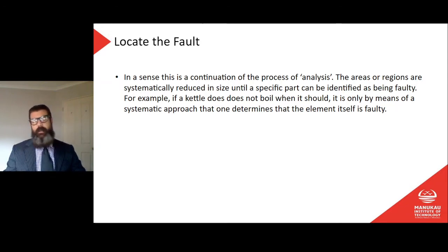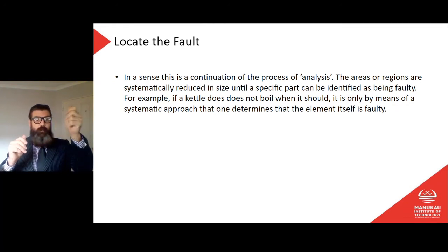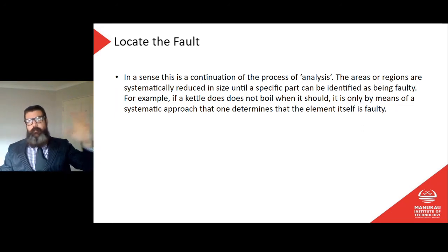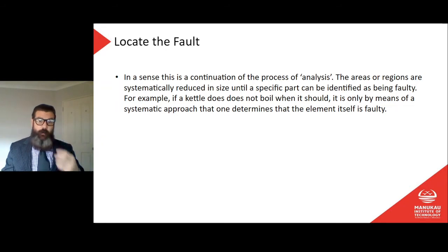Yeah, an example of this is insulation resistance testing. We've done a bit, but I don't know if we've done enough for this to really make sense to you, but never mind. I can do an insulation resistance test on a whole installation by having everything turned on at once, and I just go earth bar to main phase. Well, I have to have the main phase turned off, but earth bar to the main phase, everything else turned on, and then if there's no faults in that installation, it'll give me a very high reading in megohms, and I know that it's safe. Now, I've just done the insulation resistance test for the whole installation. But if there's a fault there, that test does not tell me anything about where that fault is.